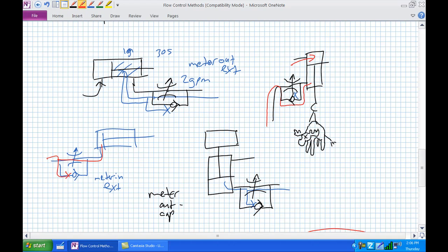So I've got pressurized flow entering here, creating a pressure differential across this flow control valve, because that's how flow control valves work. So there is pressure inside here, and basically there's pressure forcing down on that cap end. Here's our cap end. Let's say 800 psi is on that area.